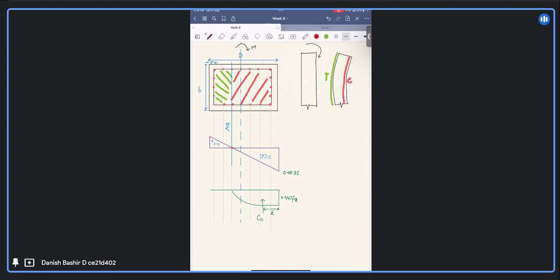In the part where the concrete is in compression, the steel bars or rebars will also be taking compressive load. So we will show the force in the rebars like this, compressive force in those, but in decreasing order because the compression is decreasing towards the neutral axis. It will be minimum, and zero here. The rest of the bars that are in the tension zone will be taking up the tension. We will show it like this. Here it will be maximum tension at the outermost reinforcement line.